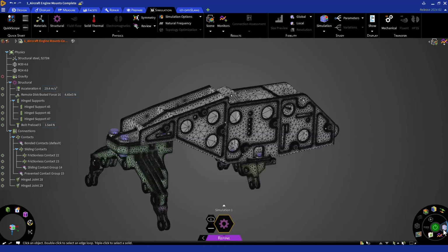Now that we have generated the mesh, we can move forward or make any mesh adjustments from the global mesh settings, or we can also create a local refinement. You can also look at the cross sections of the mesh by clicking on the Cut Plane button in the results arc. For our case, we'll need to update the local mesh, as the mesh is not as clean as we would like it to be.